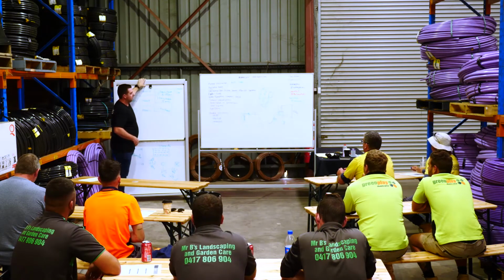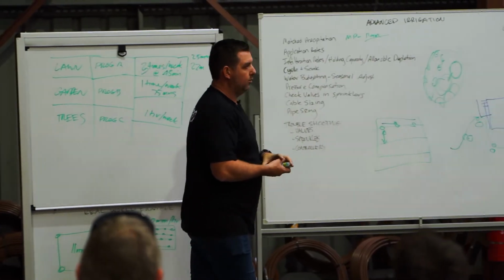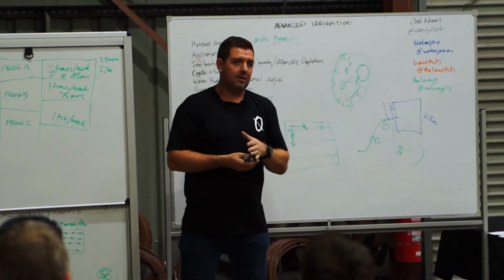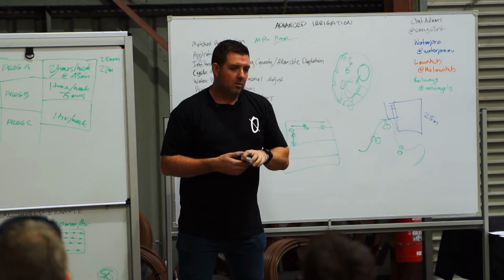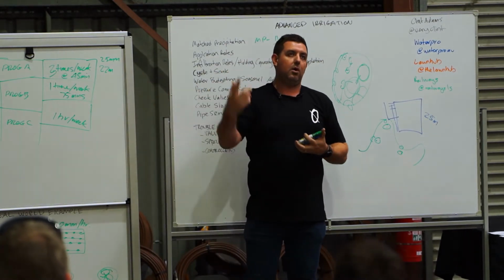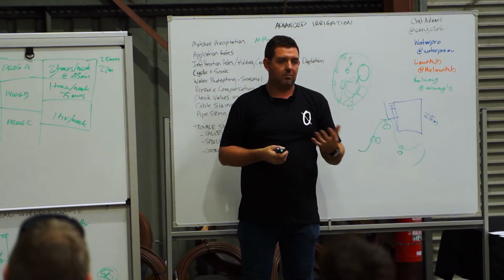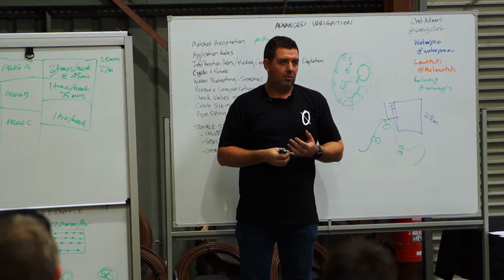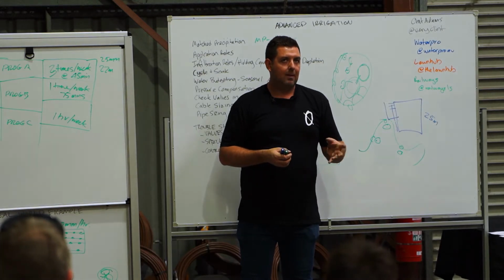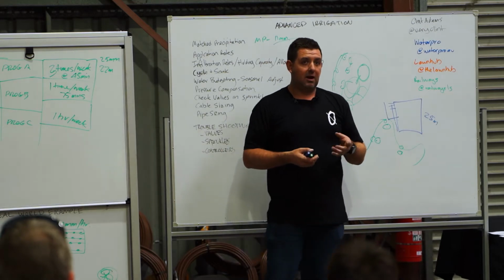There's one thing that I haven't covered that will potentially help you when you're dealing with the client at the quoting stage. Once you understand how many mil of water you're delivering per square meter of area, you can actually calculate the total demand your client might expect per annum, per season or per month, so that they can get a better understanding of how much water they're going to be buying.